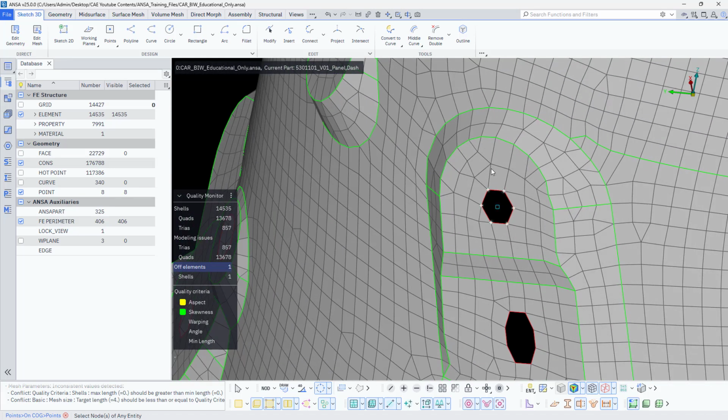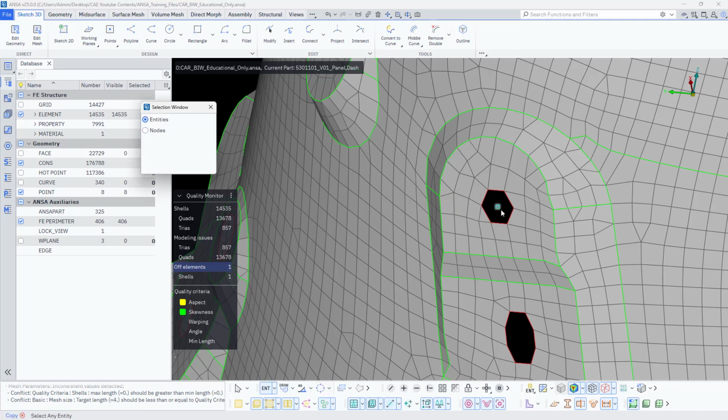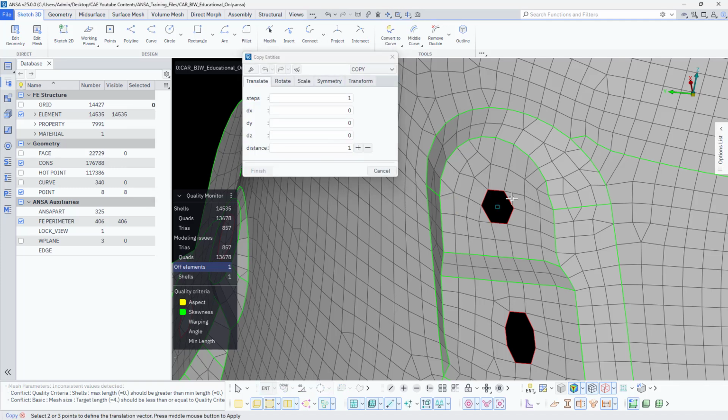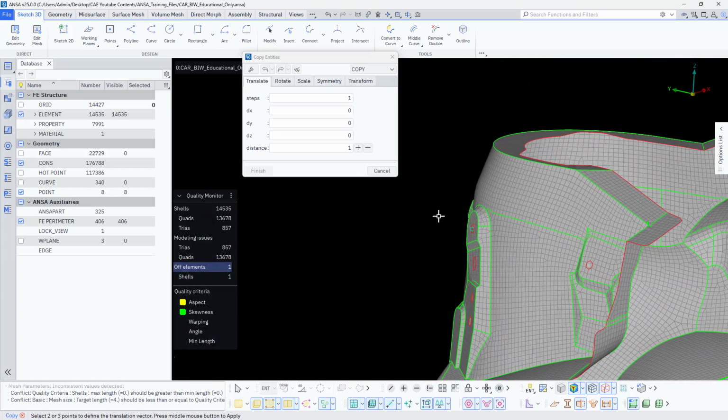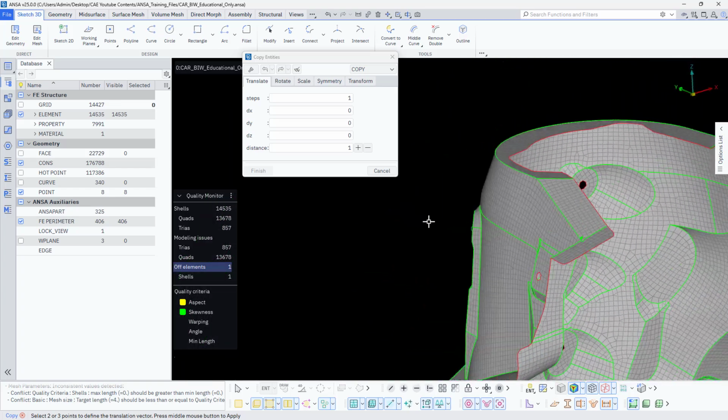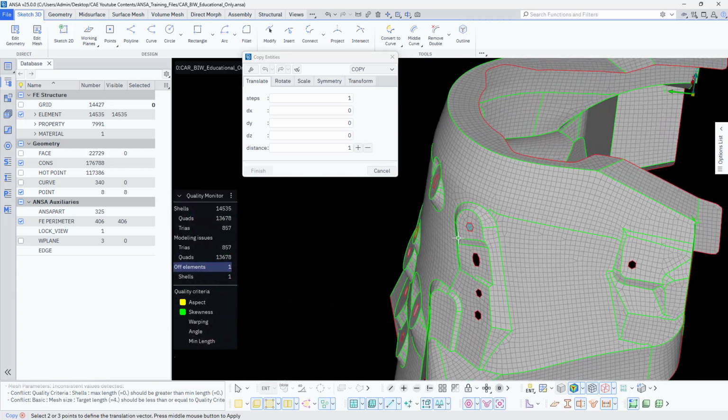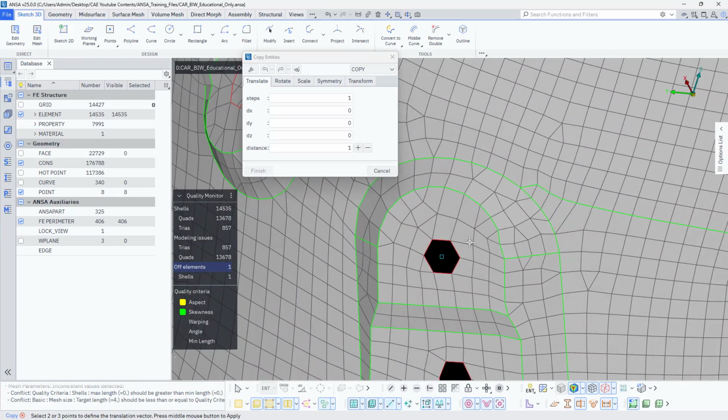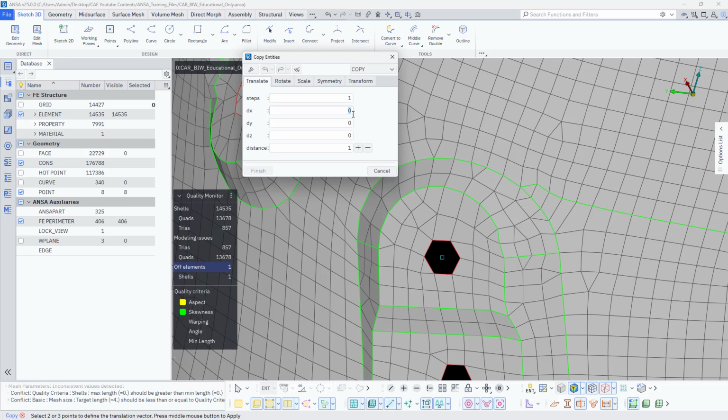Now how do we copy these points? So let's say I would like to create the coordinate system for this. You can utilize this tool, that is copy. You can activate the entity, this one, middle click. Let's say I would like to move it along X, Y, Z are quite different. Okay, let us try. Along with the X, I would like to move 10.